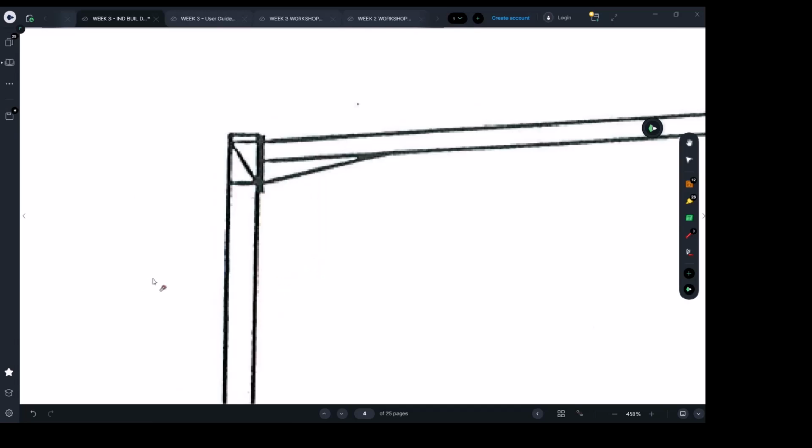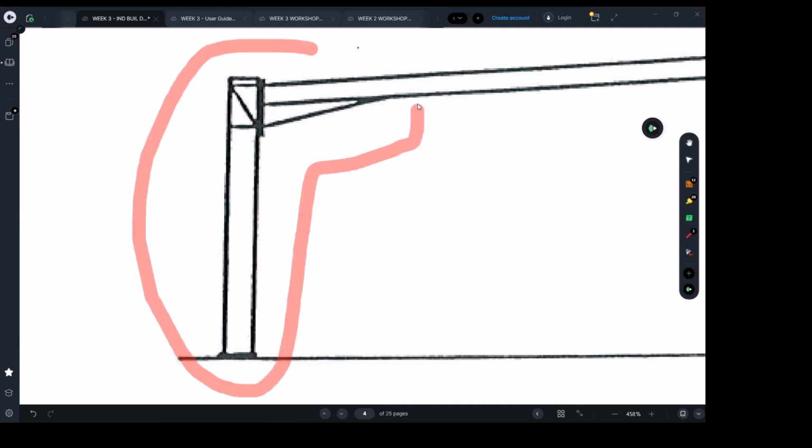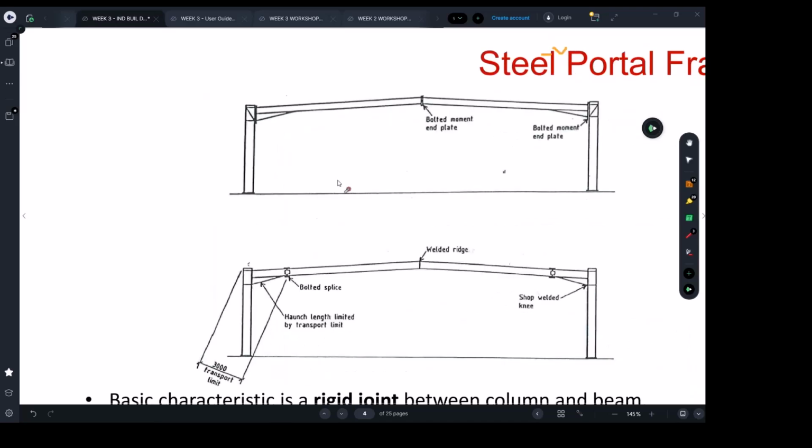This is cost, this is time. I'm going to need special engineers to come and check that those scaffoldings are safe. And you can't imagine doing this for each column. It's just going to be a lot. So that's what I was saying. There is a key consideration for construction engineers to make this joint in the factory and get it delivered. Right.